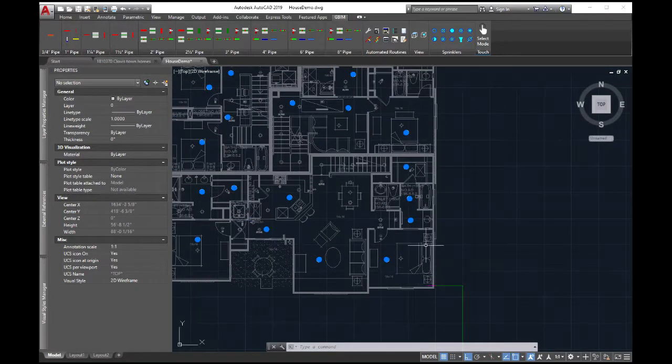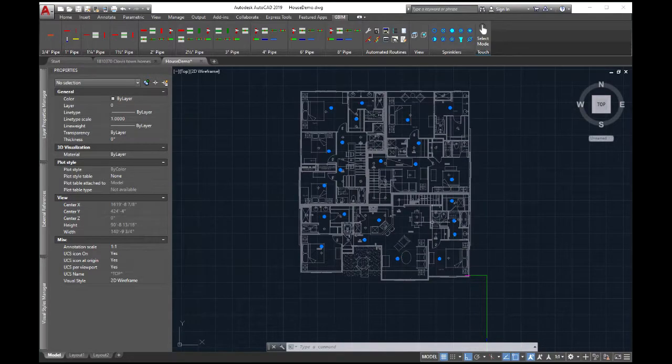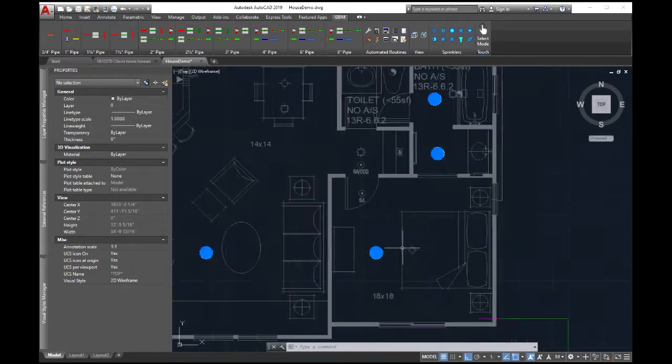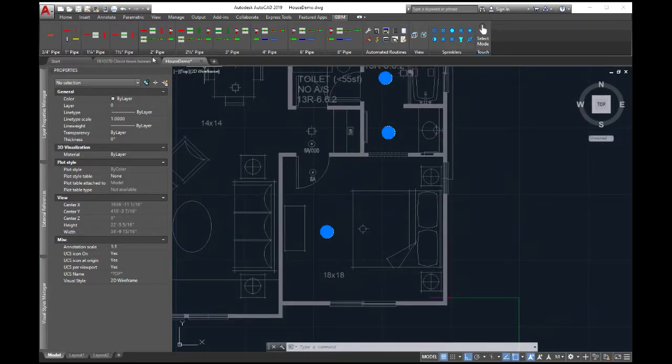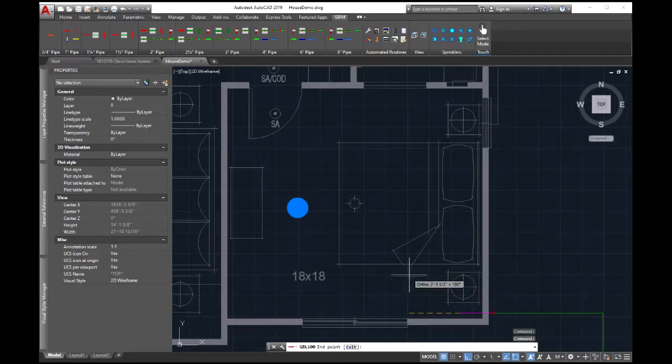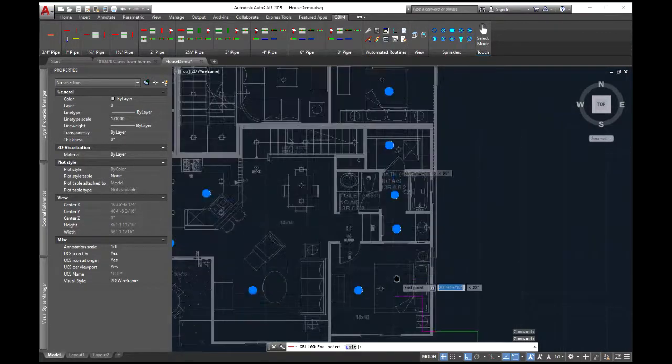And so I think we'd all agree that most houses are on some kind of a loop. Once again, we probably can't draw it exactly like this, but this is what I'm going to do. Now I'm going to switch to 1 inch because typically our looped pipe is going to be 1 inch on a house. So we're going to draw some 1 inch branch line. I think that'll come over here, and we might just do something like this and then come across here.